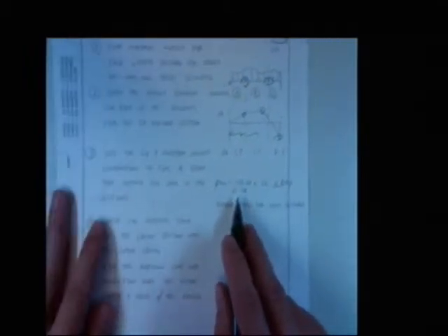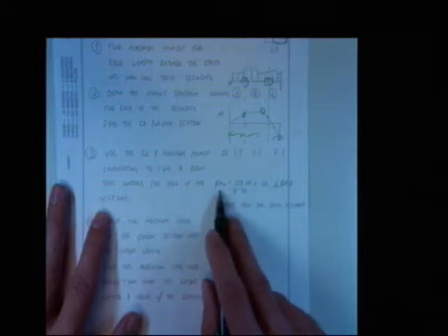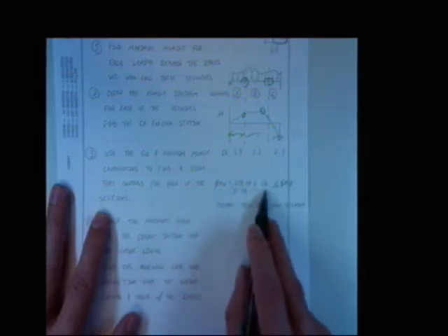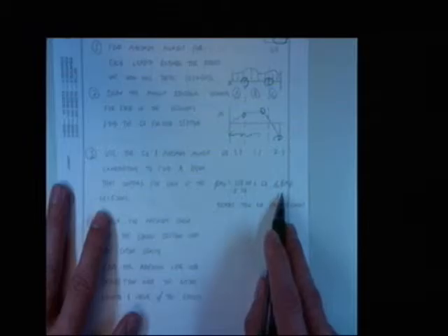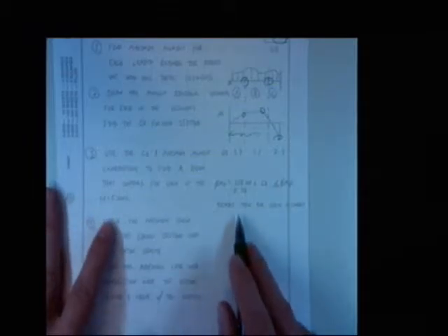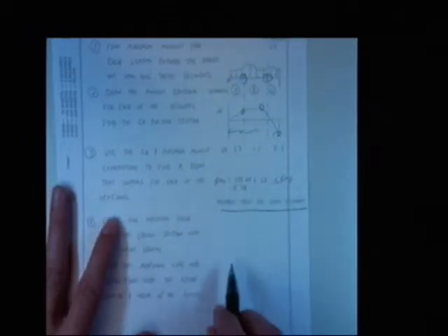Basically, you'll do that trick we talked about before. Your moment capacity is your lateral torsional buckling capacity times C sub B, and that has to be less than phi M sub P. You're going to repeat this for each segment. So you're going to almost, in a sense, do 3 different designs. And then you're going to pick the one section that satisfies all 3.